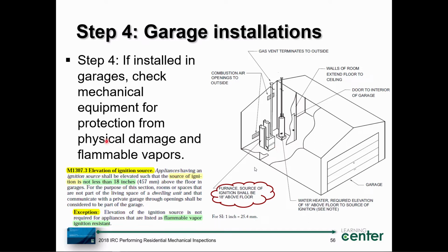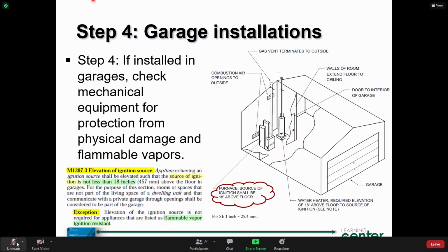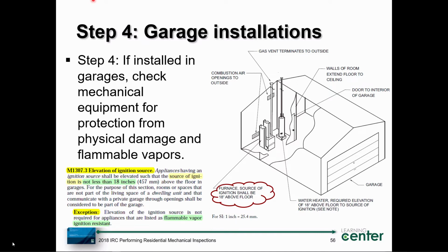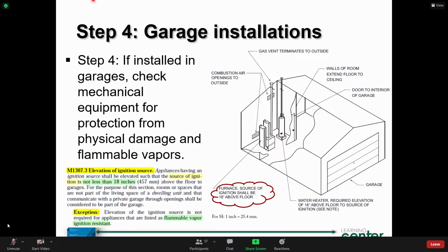What do you think a source of ignition is on a furnace like that, a forced air upflow furnace? What could possibly be the source of ignition? Natural gas. Well, Don, natural gas alone would not be the source of ignition. An igniter, yeah. What else? Any fumes, like spilled automobile gasoline, that type of thing, wherever it's sparked. Oh, a pilot light.